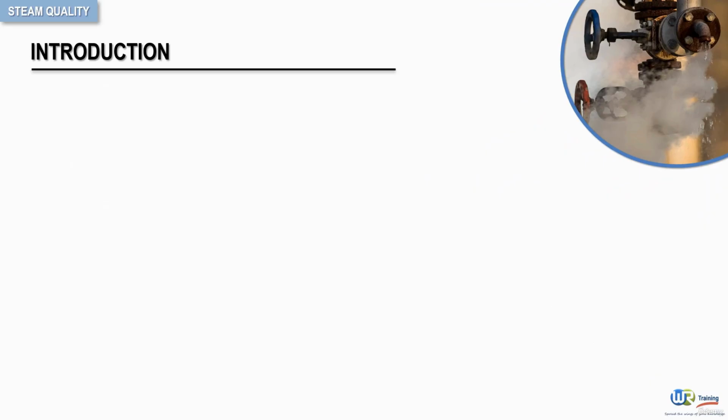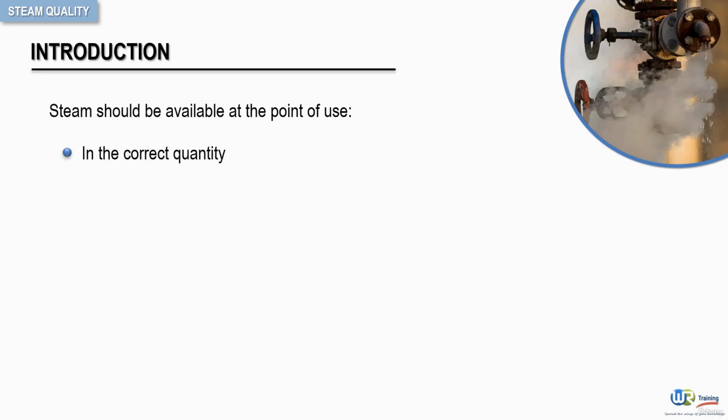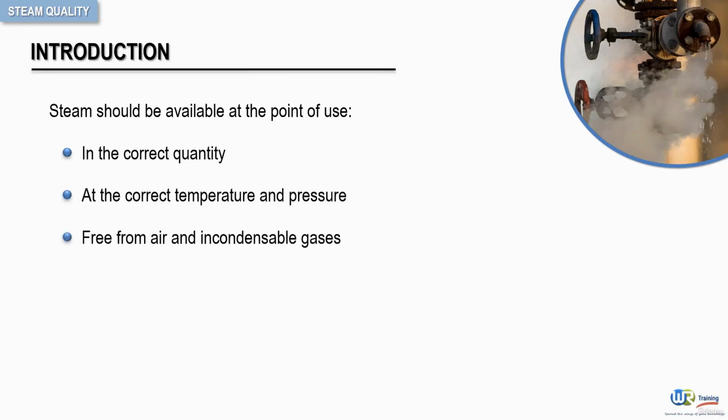Welcome to this section on steam quality. Steam should be available at the point of use in the correct quantity, at the correct temperature and pressure, free from air and other incondensable gases, clean and dry. This section will highlight the importance of these criteria.